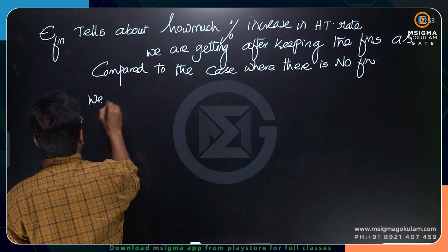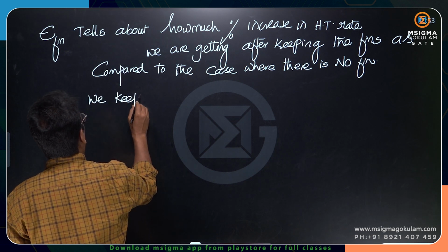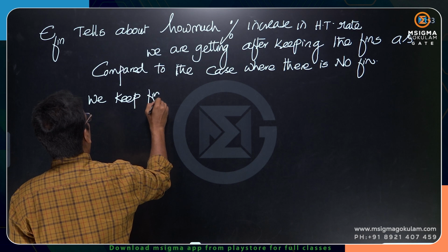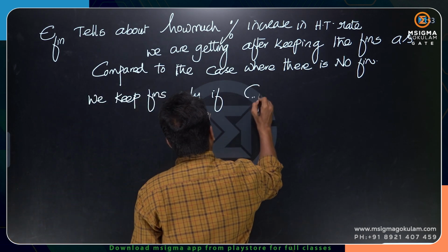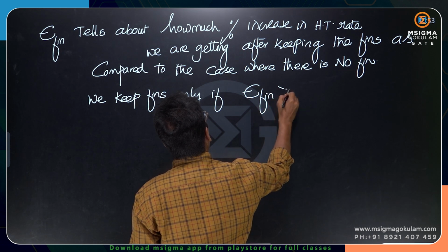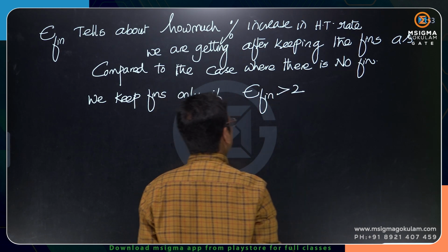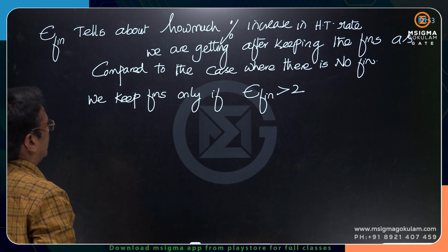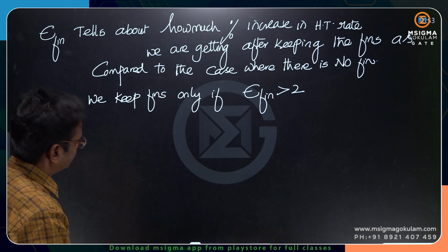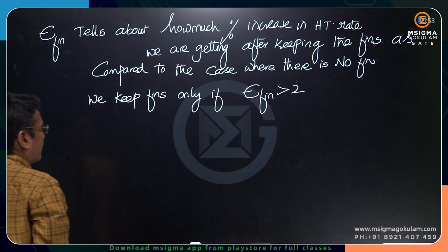We keep fins only if effectiveness of the fin is greater than 2. Okay.